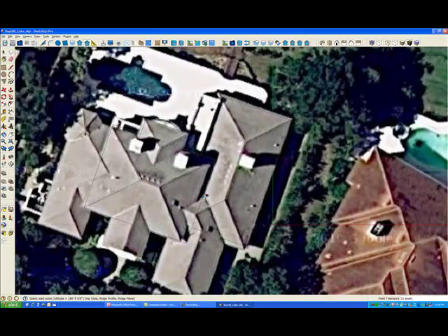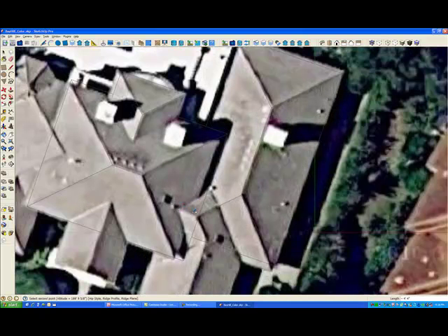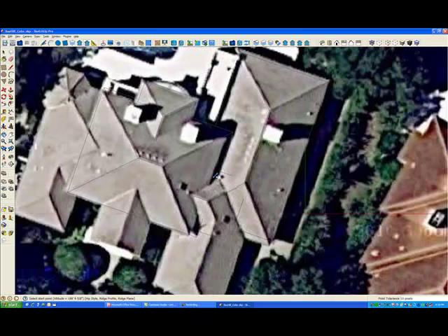So we'll intersect the existing roof plane, and our inferencing will tell us when it's perpendicular to the existing roof line. And we can do that over here as well, this small section. Here we get our inferencing, and we'll build this section that's from that edge. It's perpendicular to that roof line, and we'll line up the eave from the image.